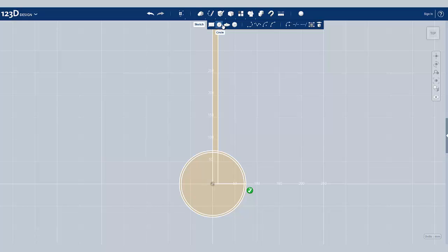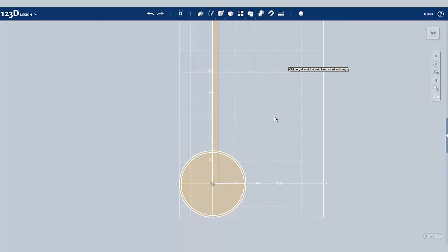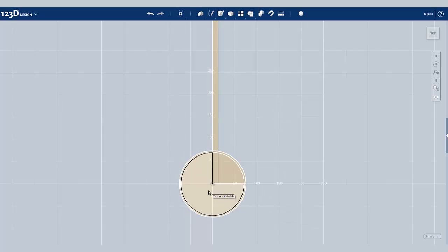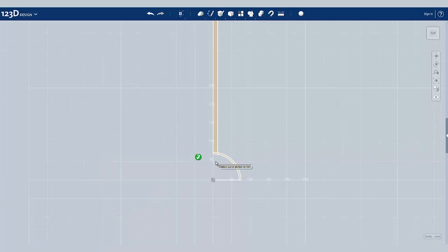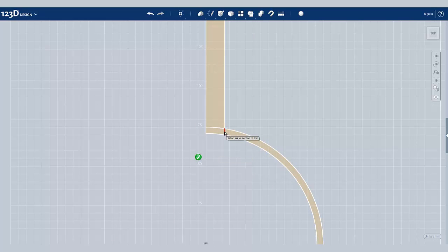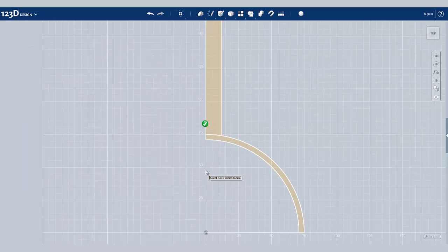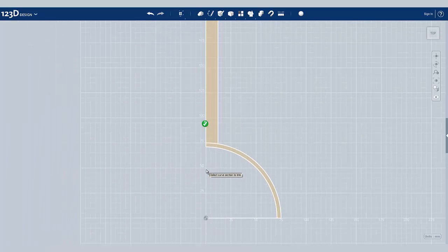Alright, well, let's get the trim tool selected. It's from the sketch tab. To use the trim tool, much like most sketch tools, you have to select the sketch we are editing by highlighting it and clicking on it. Now, we just click on the outside portions of the circle that we don't want. Let's also get rid of these parts of our shield in here, and this extra small line up here. You'll see why that's important in a moment.